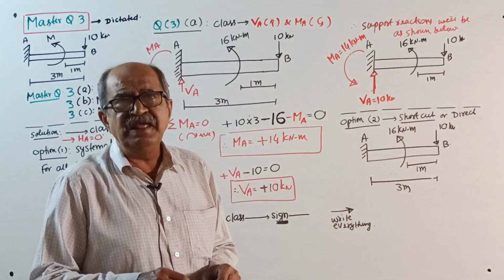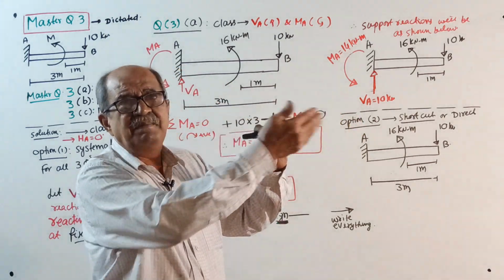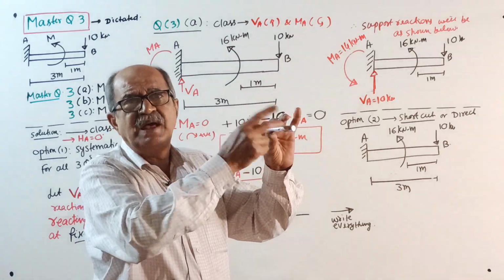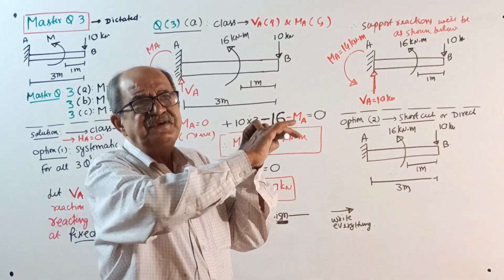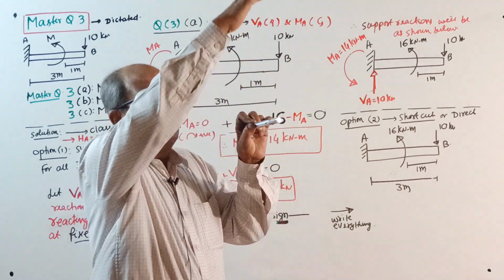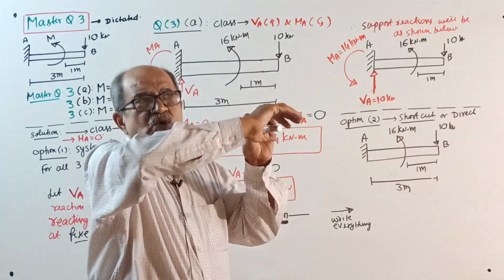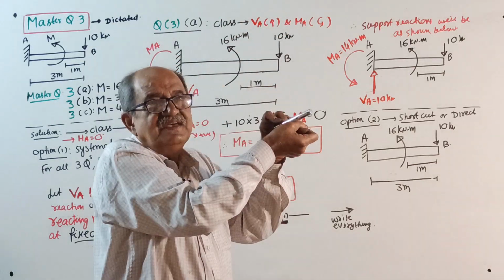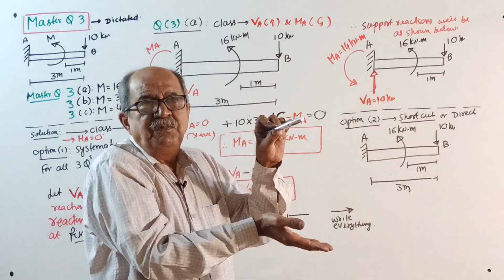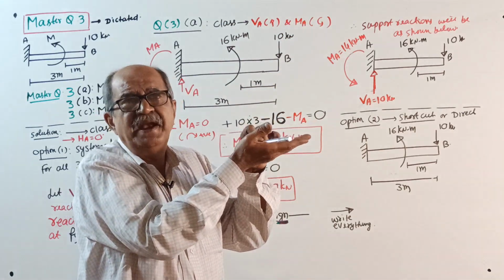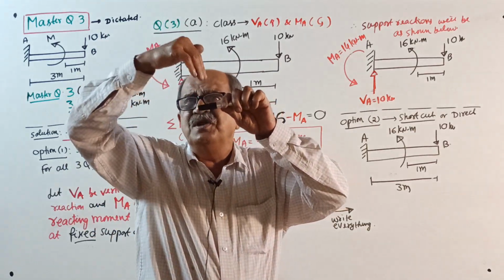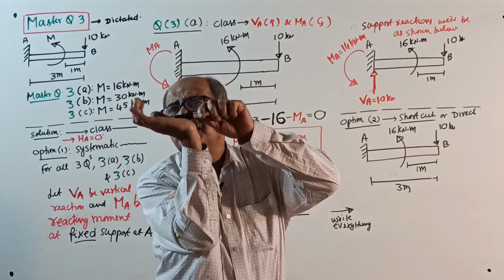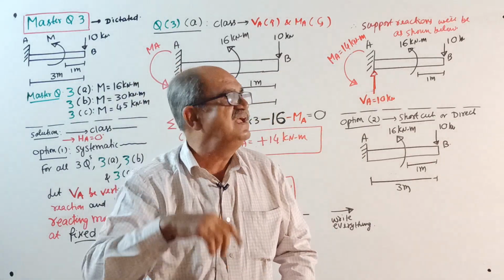In the case of a cantilever retaining wall, you design both the heel slab and the toe slab of the base slab. Just believe me now. When you consider the heel slab, the downward load is predominant, so it will bend like this, and the upward pressure usually will be less predominant. But when you consider the toe slab, the downward load is very small and the upward pressure is high. It will have reverse bending.